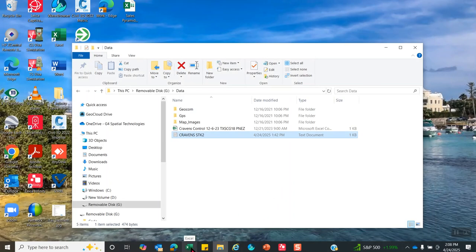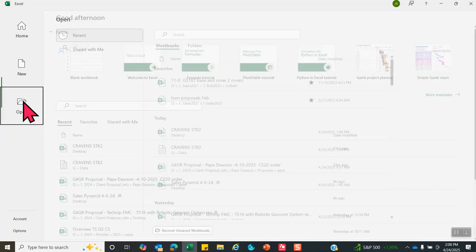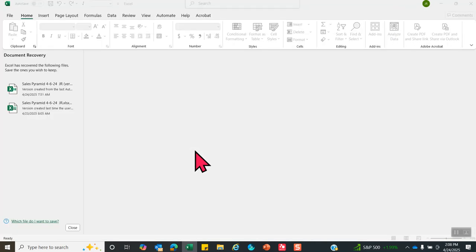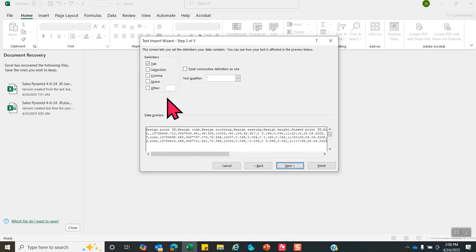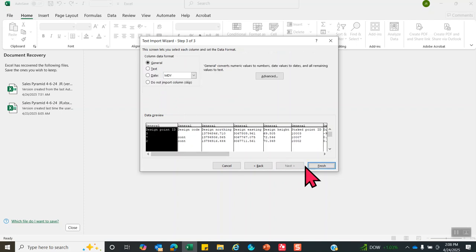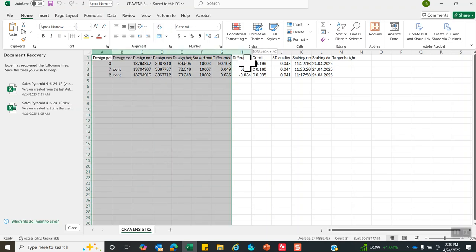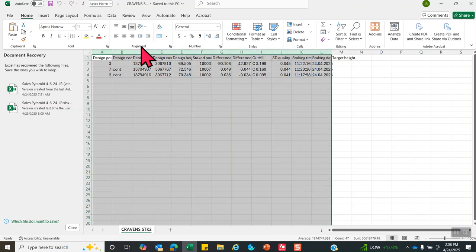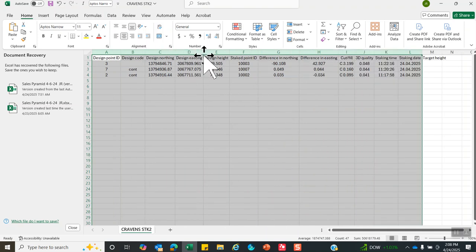Okay, so I go to Excel and import that in. So come in here, open, pick that job there. I'll say it's delimited, hit next, a comma. It creates these fields, hit next, and finish. And then once again, all the information's here. I could center that. And then once again, you can just maximize this. And there's our point ID.